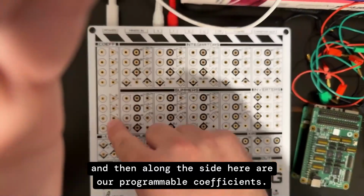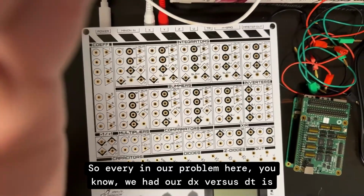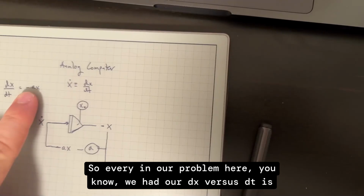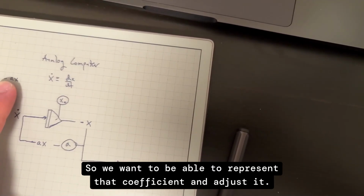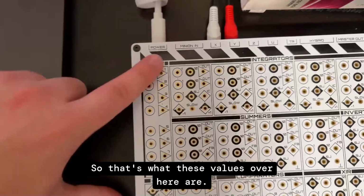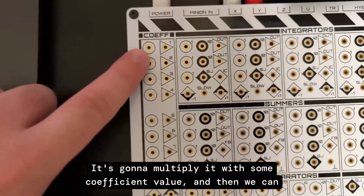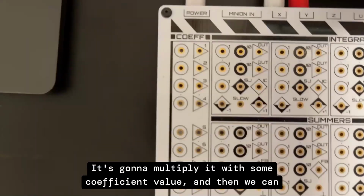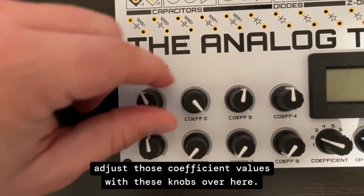And then along the side here are our programmable coefficients. In our problem here, we had dx over dt equal to minus a x. So we want to be able to represent that coefficient and adjust it. That's what these values over here are. We take an output signal and pass it through this one, and it's going to multiply it with some coefficient value. And then we can adjust those coefficient values with these knobs over here.